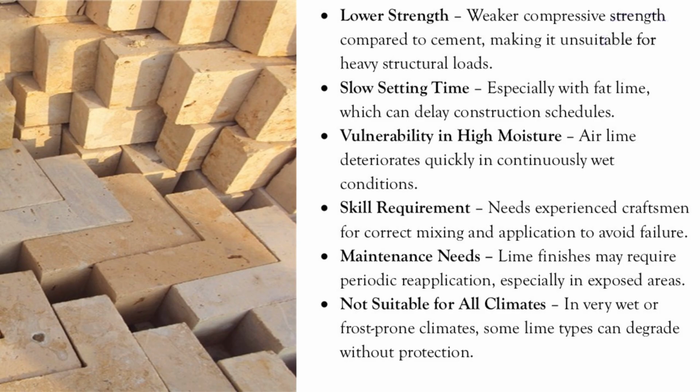So first is lower strength. Weaker compressive strength compared to cement, making it unsuitable for heavy structural loads. Then slow setting time, especially with fat lime, which can delay construction schedules. Now the vulnerability: air lime deteriorates quickly in continuous wet conditions.